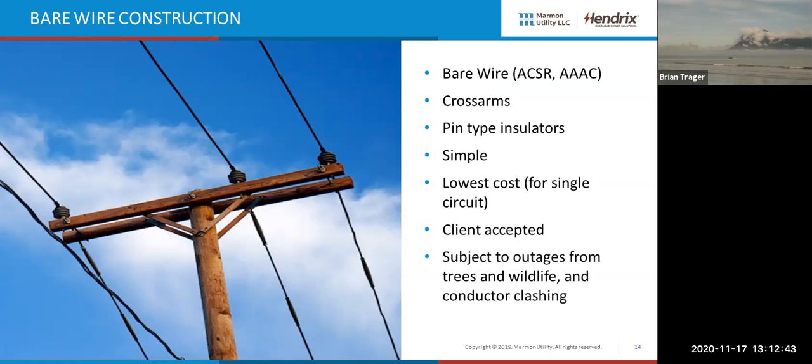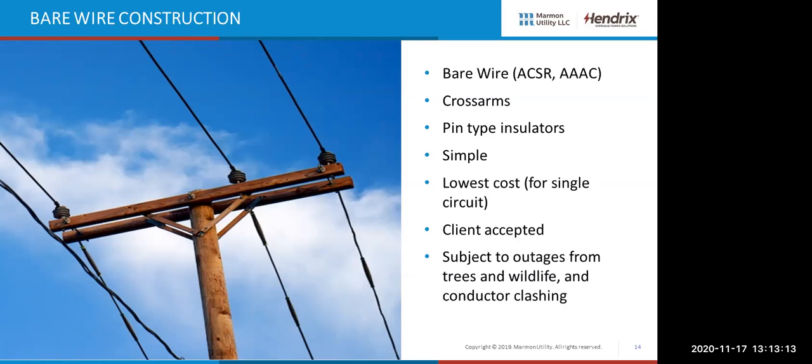National Electrical Safety Code Rule 230D tells us that if there is not a concentric neutral on that jacket, that cable is not insulated, it is covered. So that's the difference between covered wire and insulated wire. It's covered and we have to treat it like bare wire for all clearances, except clearance to edifices, and we'll talk about that later, and safety and work practices.